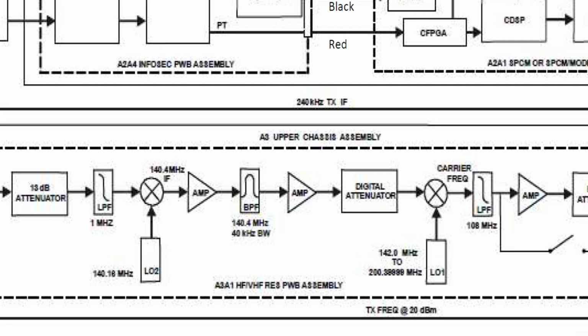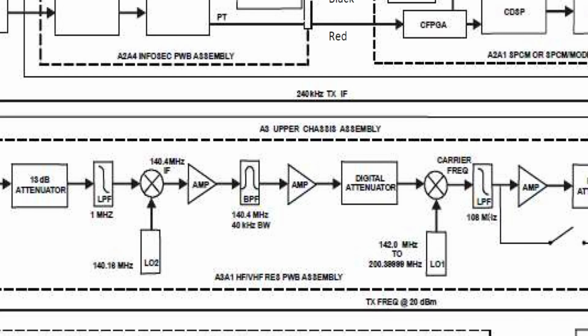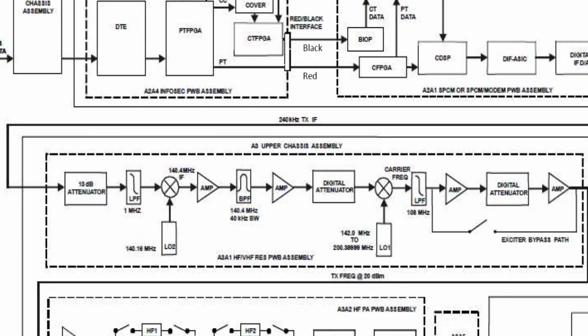So our total gain may be really high coming into the radio. Maybe you have somebody who's talking super high, or their voice is really quiet, or whatever. This attenuator is going to remove 13 dB of gain basically from that signal, so that the signal strength is not too hot coming into this next couple portions we have here, because we have a lot of filters, amps, attenuator. We got some small circuitry coming up in this next section in A3, and we don't want to blow that small circuitry. Make sense? Okay, cool.